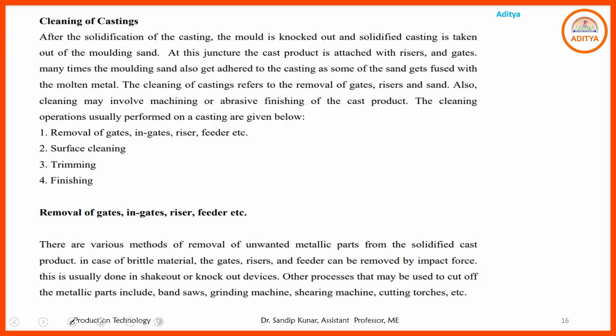What is the cleaning of casting? After production, after casting, in the final product we have got using the casting process, some extra metal, some debris, some impurities stick to that particular product. So removal of that debris from the casting is required. It is mandatory. Otherwise, the outer surface finish of that product will not be good.